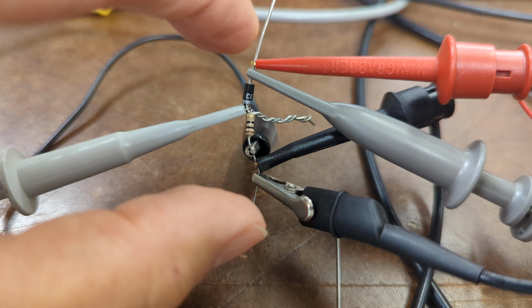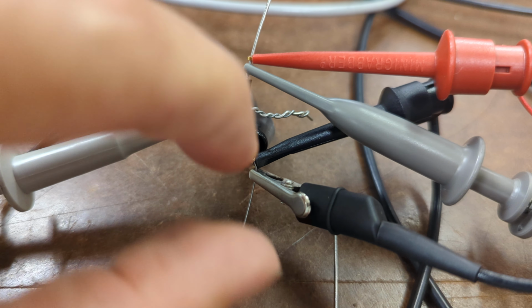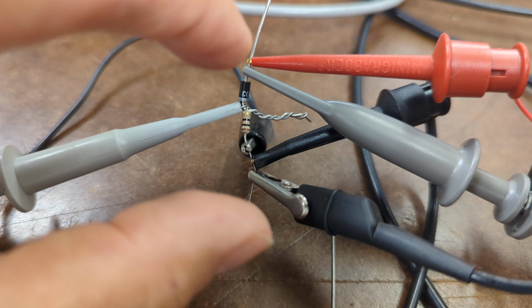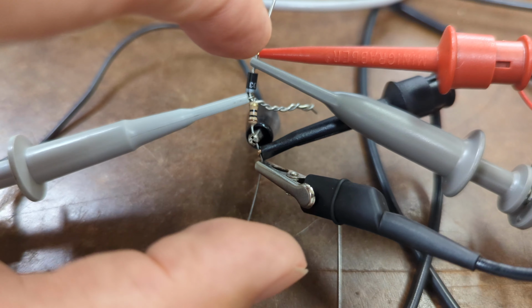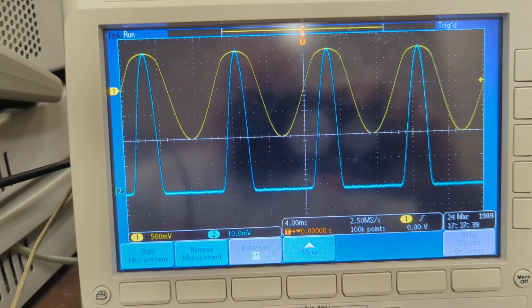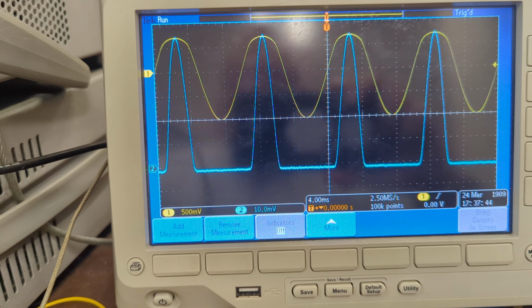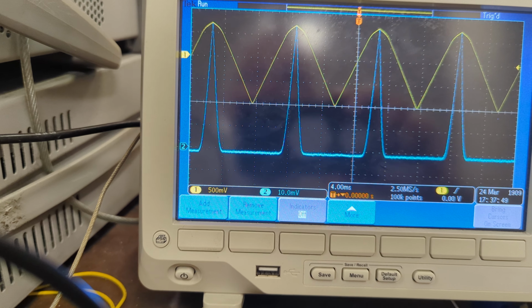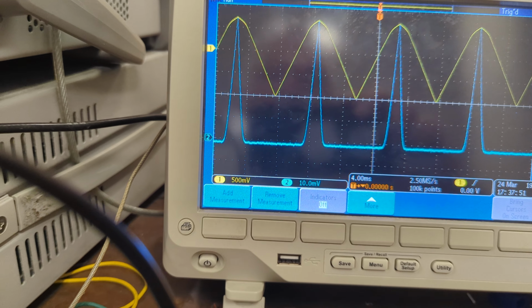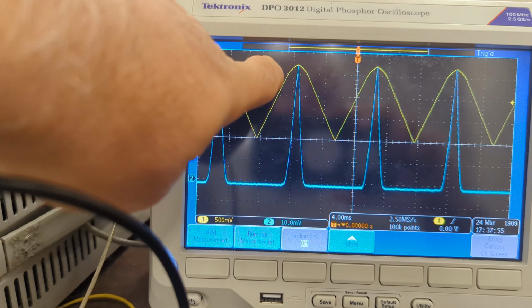So we apply and measure voltage 1, and we measure voltage 2, and because this is only 10 ohms, we're kind of assuming the voltage across the diode and the whole device is the same. Now, I happen to like using sine waves, but really one should use ramps for this kind of thing.